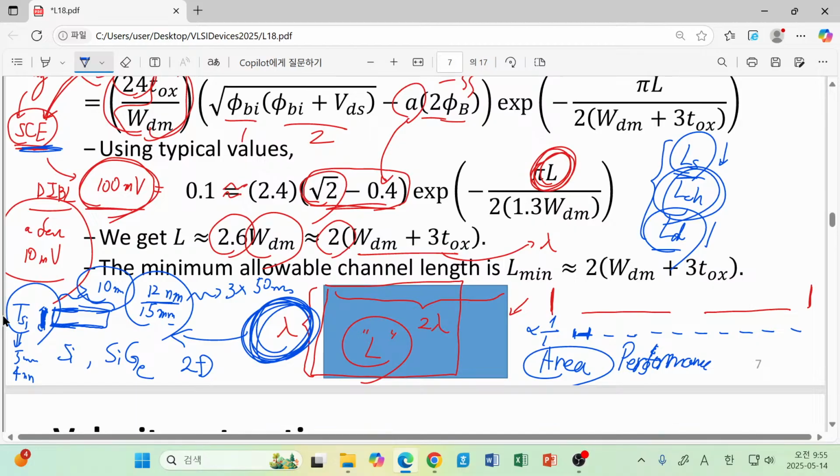So the natural consequence is that reducing the lateral length, the channel length L, is not that difficult, but in order to get reasonable electrostatic property, we reduce the silicon thickness even further, not 5. Our goal now becomes 3, 2, 1. And the next question is, can you make 1 nanometer thick silicon, 2 nanometer thick silicon, 3 nanometer thick silicon?